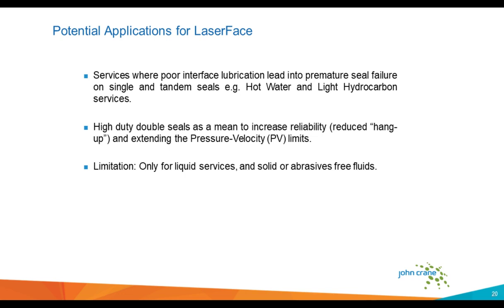The limitation of the seal is that it is only for liquid service, and it has to be a solid or abrasive-free, clean fluid. And I might also add that the laser face technology can be applied to most conventional seals, or most of the seals already out in the field.